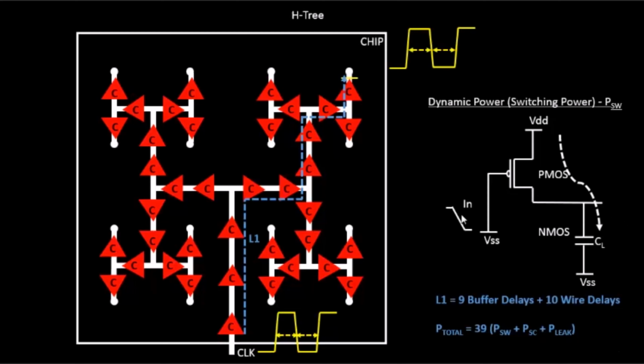This happens whenever there is a switching from logic 1 to logic 0, consuming around 20 to 30 milliliters of water. Why does it happen at every switching? Because whenever the next switch happens, from logic 0 to logic 1, this particular tap gets opened, and all the water from this bucket gets drained out through this NMOS. Hence, after every switching, some amount of water has to be present in this bucket again. That is the basic phenomenon of switching power.